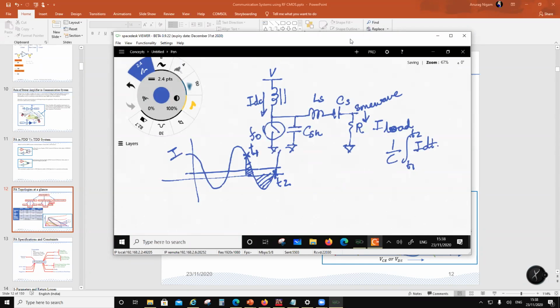And if you see the current waveform, the current is also 0, right? So I have a 0 voltage and 0 current. I have a 0 voltage across the capacitor, and in the parallel combination, the current has also decayed to 0. That means when I'm switching on the switch, the capacitor is storing nothing on it. So the loss which you would face because of energy stored in parasitics will be gone. That means the switching is smooth.